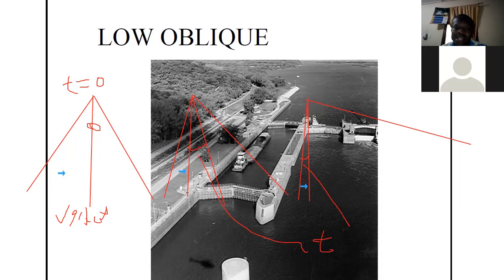which we are not really interested in for oblique photographs, because we have intentionally tilted it just so that we can have a certain view. It's not good. We don't want to use oblique photographs for anything in engineering. We'll find out later that even where we have tilted between 0 and 3 degrees, we have serious corrections to make. We have to use an auxiliary coordinate system in order to measure from a camera which is unintentionally tilted between 0 and 3 degrees. Are you okay? All right.